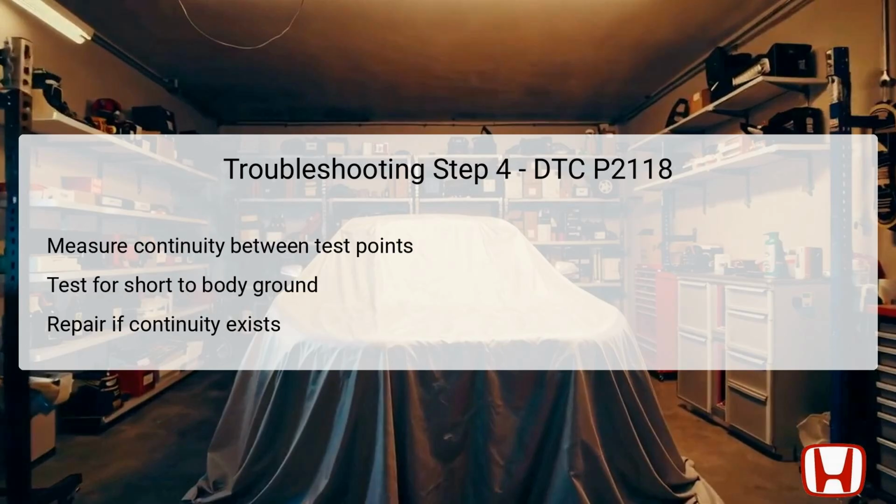In this fourth troubleshooting step, the objective is to measure continuity between the MTR1 and MTR2 lines again, but in a different configuration. Verify that the vehicle remains off and the relevant connectors are disconnected to ensure accurate measurements. Here, you will be testing continuity between female terminals number 1 and number 2 of the throttle body 6P connector. And the second test point is the body ground.